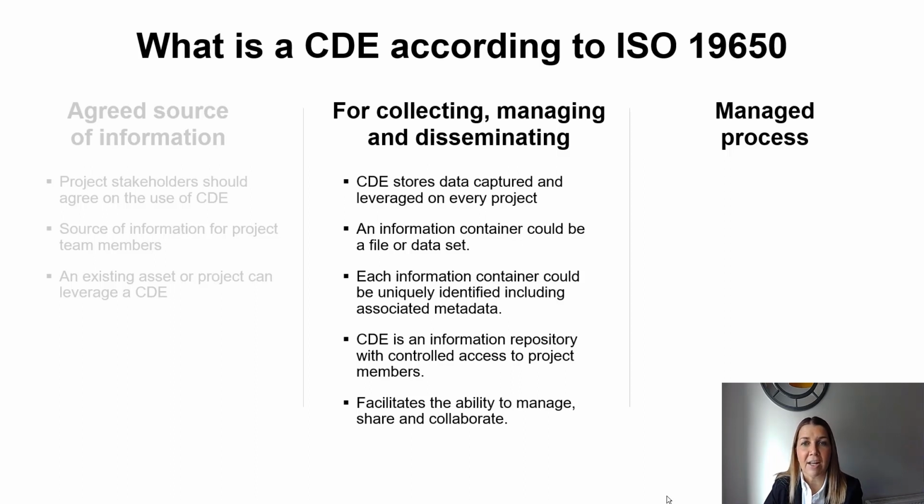Each information container can be uniquely identified, including associated metadata. Each information container should have a unique ID which follows the agreed project naming standard, and associated attributes to detail the status code, revision, and classification.